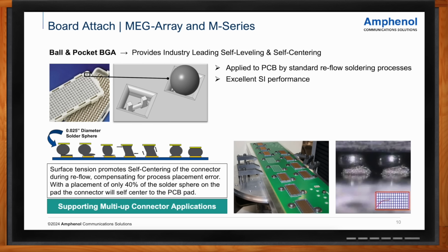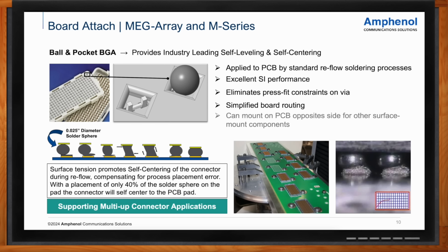And if you just had the solder sphere, if you could picture it without a pocket, just residing on a contact in the air, as you reflow it, both at the factory side, but then at the customer side, it's more likely to want to slump to one side. And now the true position, the location of that solder sphere is not as advantageous. But now it becomes even more impressive and helpful to the customer.